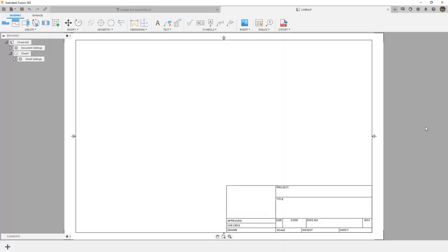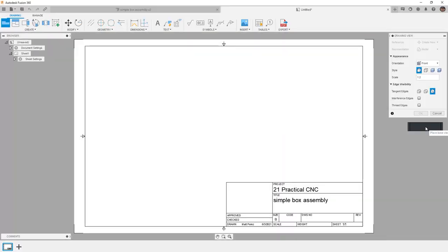Most of the design elements in Fusion 360, such as animations, renders, and even the manufacturing toolpaths, are all contained in a single design. However, detailed drawings will create a new design file for you that'll be saved in the data panel. To get started, we first need to place a drawing view. Note that the Create New and the Model Representation are grayed out because we've already decided how we're creating those references. But we can modify things like the orientation.